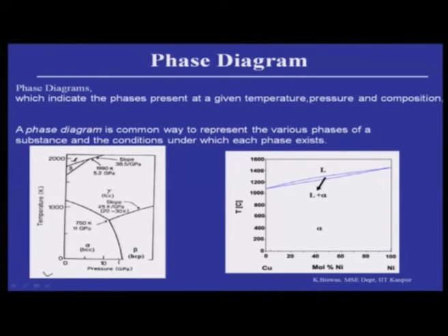So that is what people say, if you dig the earth and go to the bottom, before the liquid iron comes, you will have HCP iron present at a high pressure. Now if you heat it up beyond 910 degrees Celsius, which is nothing but 1183 kelvin, BCC alpha iron will transform to gamma iron. That is what you see here, and gamma iron is FCC iron, very stable over a wide temperature and pressure regime. But when heated beyond a certain temperature, gamma iron again will transform to delta iron, and at 1539 degrees Celsius, delta iron melts to liquid.